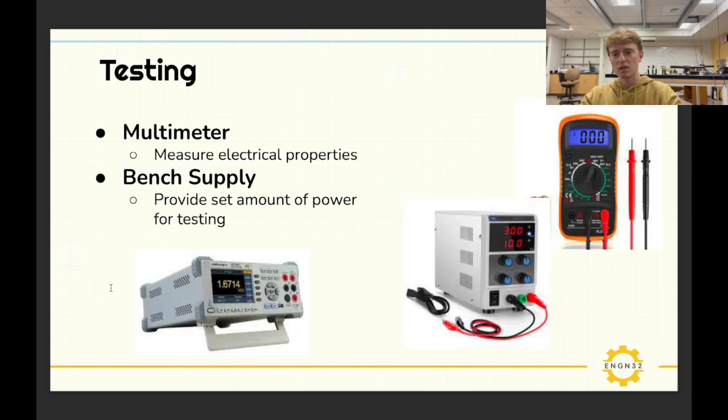All right, basic test equipment. Multimeters are very important, very basic, very fundamental. You'll see them in the lab. We have large bench multimeters, which look like the thing in the image here. You can do a 4-wire measurement, for example, if you want to measure some resistance really accurately.